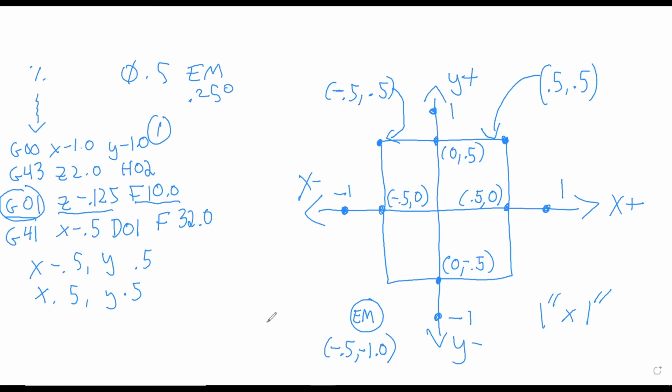So once we move to our new location using cutter comp, we can now program to the part's geometry, and the tool and the machine will compensate for the tool for us. So you see my next line right here. We go to X -0.5, Y 0.5. So we're climb cutting, which is going to give us the rigidity that we want in the CNC machine.